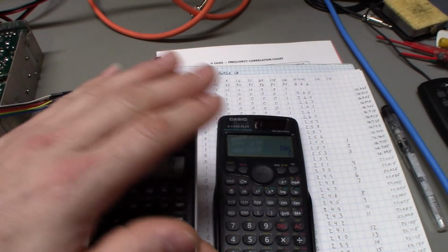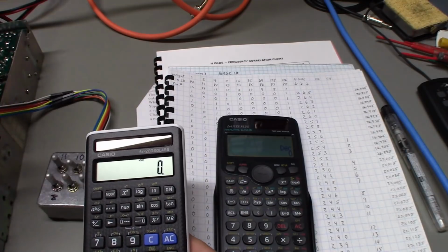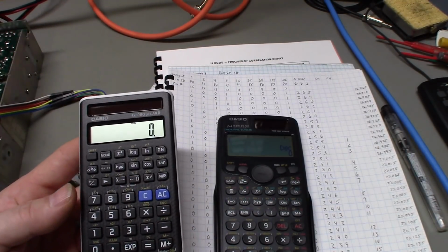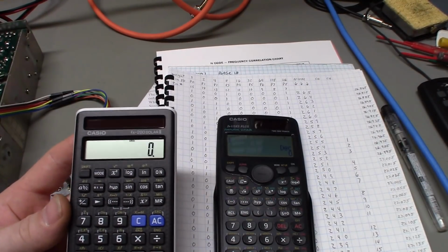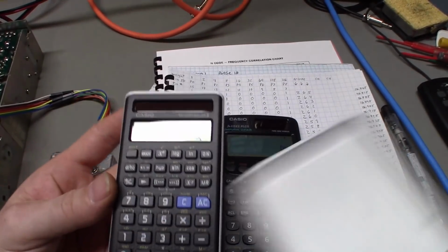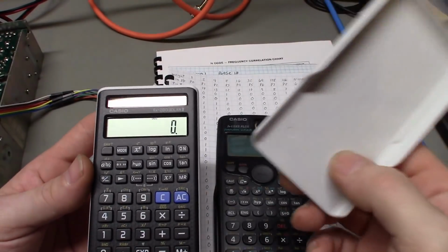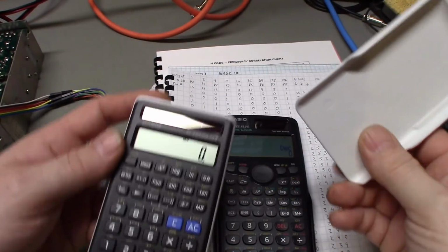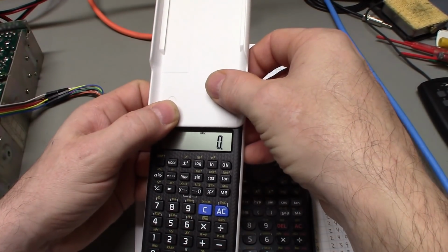So what if you were to get into the shade a little bit, where it's varying from power to no power, power to no power? Well, what they have in there is just a high-value ceramic capacitor as a storage reservoir. Dave found where that is on there and increased it, and I did the same thing. I used a different value. I stuck a 47 microfarad tantalum capacitor in there, but look how long this will last with absolutely no power going in.